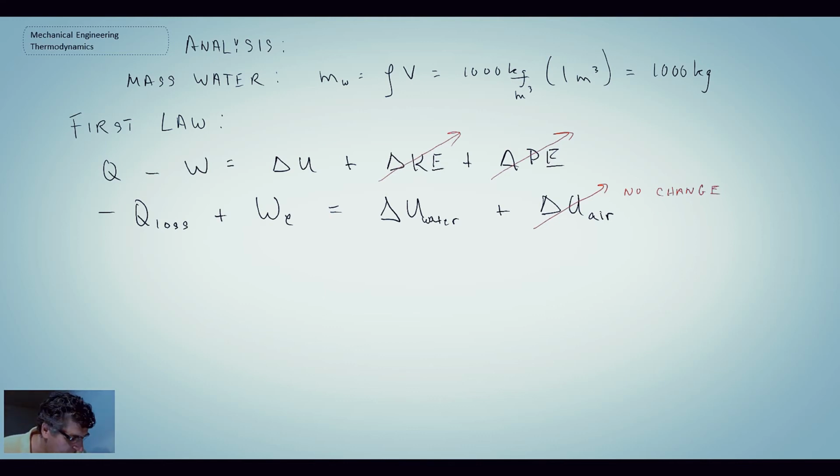Now what we're going to do, let's evaluate the amount of heat transfer coming out of the house. We said that this is going for 10 hours, and the loss was 50,000 kilojoules per hour. So we can write 50,000, and then I'm going to write this in joules now, times 10 to the 3, times 10 hours, because we have this going for 10 hours, plus the electric heat.